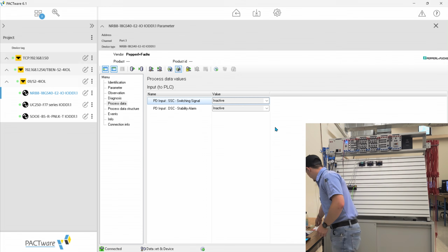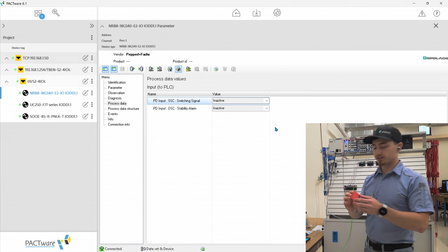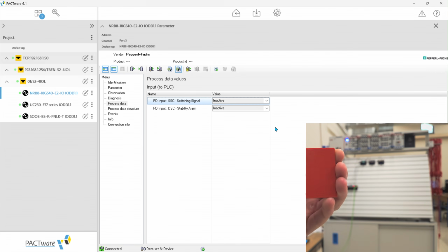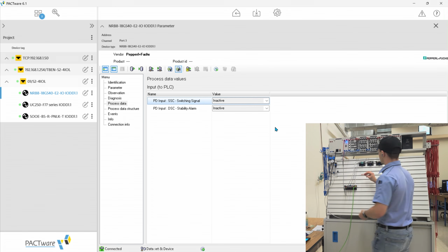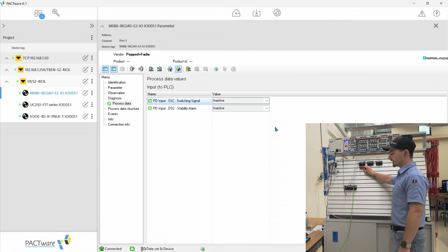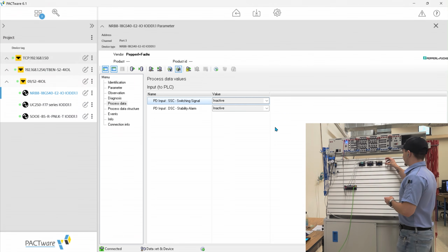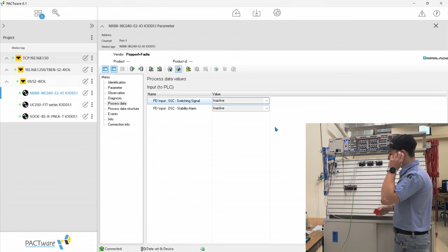And now, I have different material as well. This is just a piece of plastic. Make sure that this can see it. That's just a piece of plastic. Okay, we'll stay on the inductive sensor. If I go up to that, then it's not reading it. Okay? And it's obviously because it's plastic, and this sensor is looking for metal.